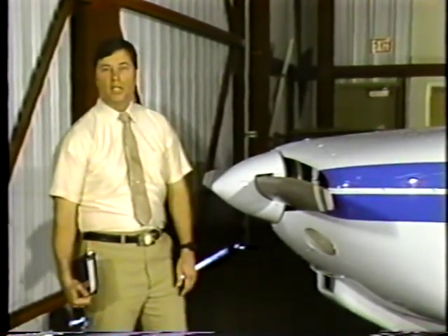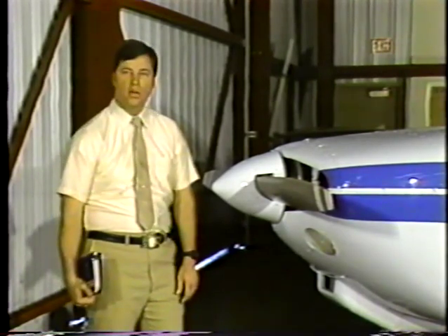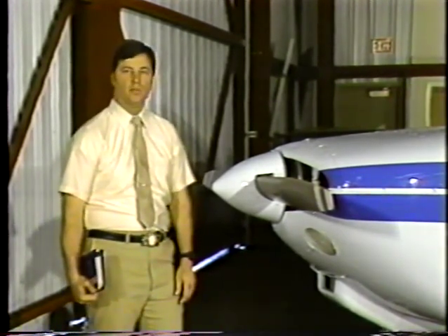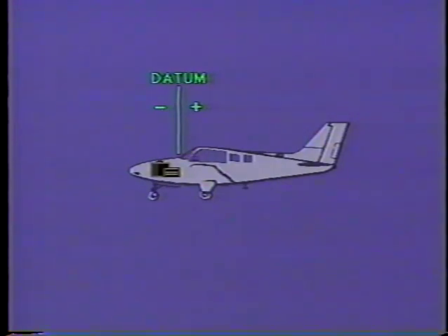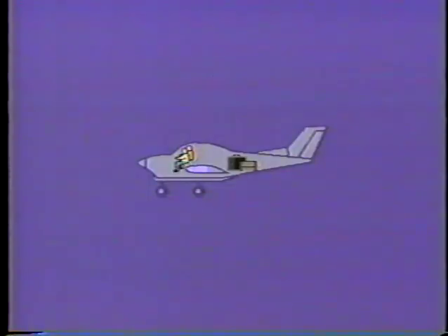Objects placed aboard the airplane and the airplane's center of gravity are measured in inches from the datum. The location of the datum is arbitrary, and it may even be located with the weight objects placed in front of it, like it is for this twin-engine airplane with a nose baggage compartment. In that case, the arm will have a negative value as well as the moment. Once we have the arm of all the objects aboard the airplane, we can use our previous formula of weight times arm to arrive at a moment value for every object aboard the airplane.